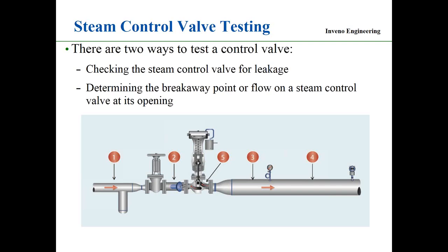As I start to apply the control signal into this valve, at what point does the valve start to pass steam? So if it's 4.0 milliamps, I go 4.4 milliamps, is it passing steam yet? Or does it start to pass steam at 5 and 5.5? It's very interesting when setting up a control valve, sitting there with a 4 to 20 milliamp generator and seeing exactly what point does steam start to pass through the valve.